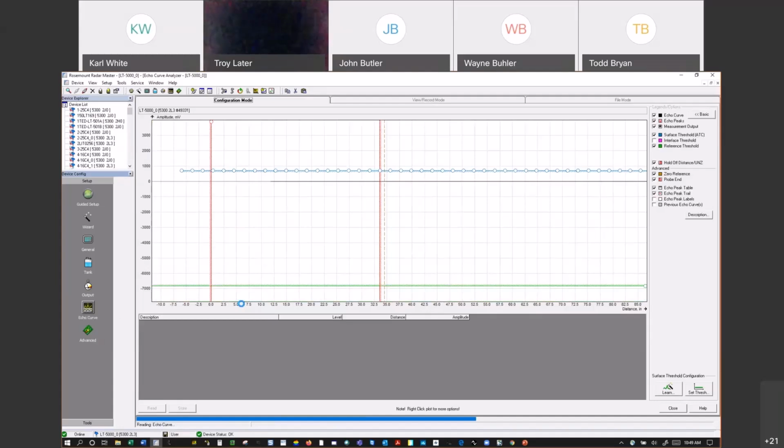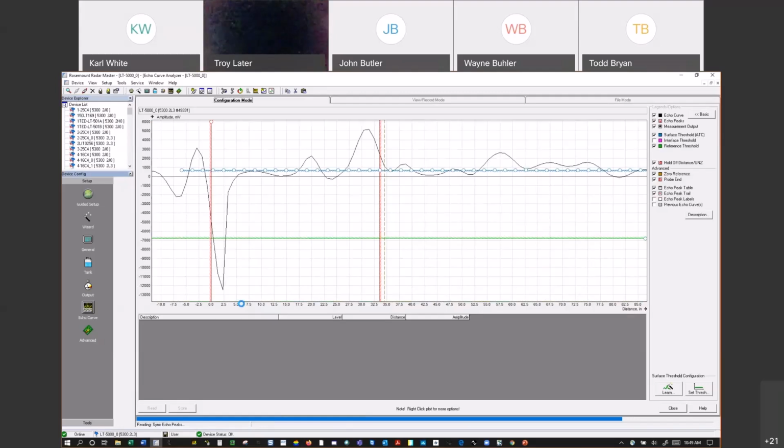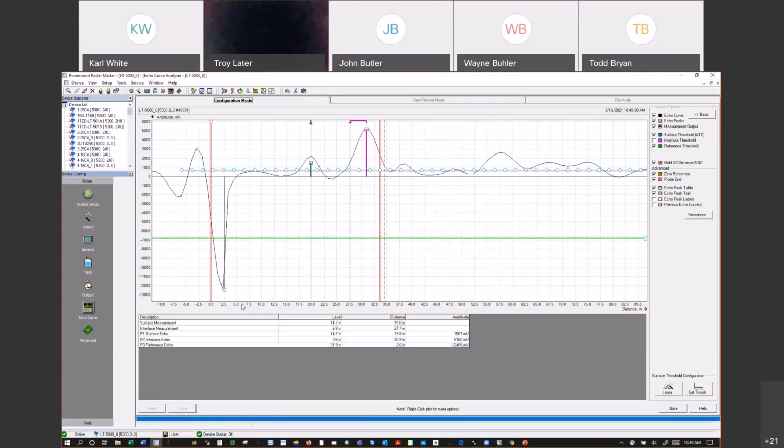So with the coax, we have a new probe type called a large coax. It's almost double the diameter of a standard, like 1.7 inches diameter. And instead of having holes in it, it has slots. So there's no space on that entire probe that doesn't allow fluid into it. If you use a large coax, mostly in a chamber application, I'm thinking, you could go down to like 1 inch of product thickness with that one. Okay. So with the single cable, it still goes down to 2.5 inches. So it's half what it used to be.